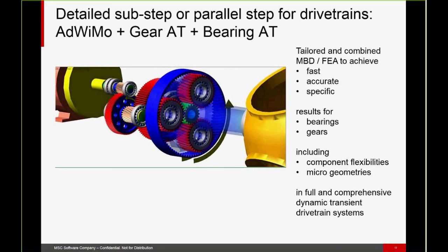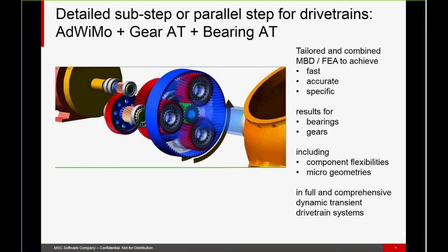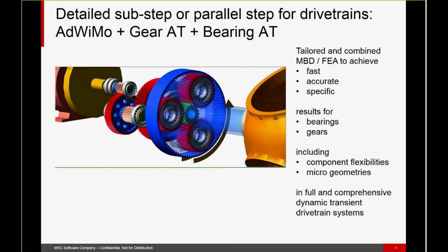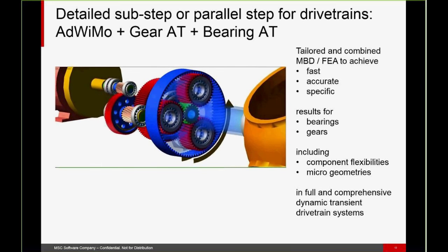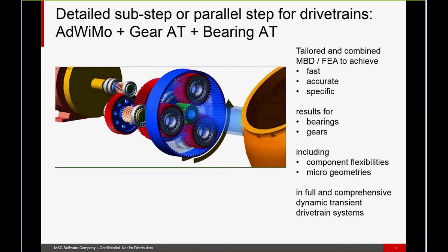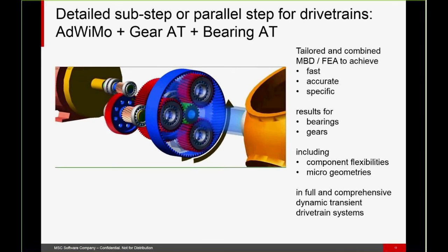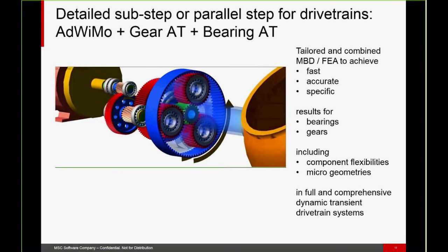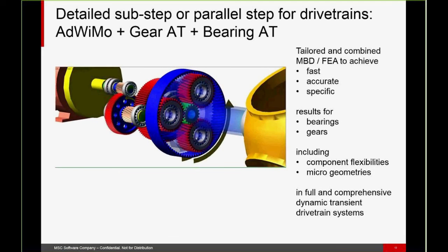But of course, you can use your loads coming directly from the blades to evaluate your gearbox. And therefore, you need a very accurate gearbox, because the blades have, of course, not a linear load. It's non-linear and it's a vibrating load. And this has an influence on the lifetime of your components in a drivetrain.